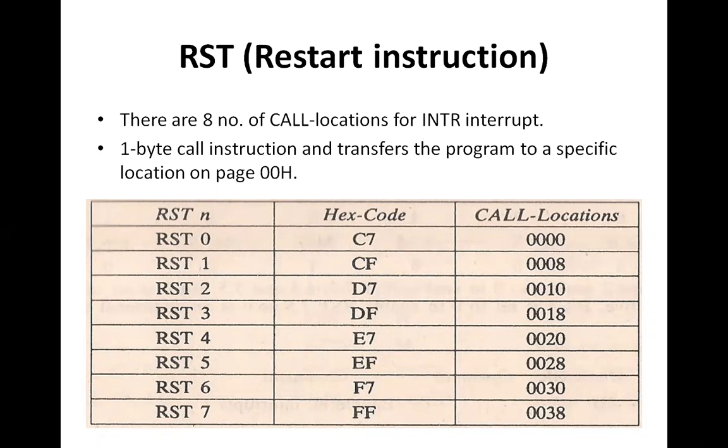RST instructions are executed in a very similar fashion as we execute the call instructions. What happens when the call instruction is executed? Whatever is the program counter content, which is the next instruction's address, it is stored in the stack, and then it will move to the subroutine. Similarly, whenever an RST instruction is executed, whatever is the content of the program counter, it is saved temporarily in the stack.